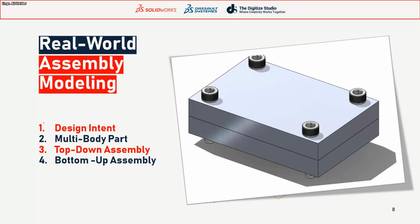Now moving forward with the real world applications, first of all, the design intent. For the design intent, we mean that in order to start the model, from the concept, from the very first stage, you must ensure what the parameters are that may change in the future. You also have to understand which parts of our design are dependent on each other, what dimensions we may have to modify in the future, maybe the wall thickness, and also which features must be modifiable in the future.